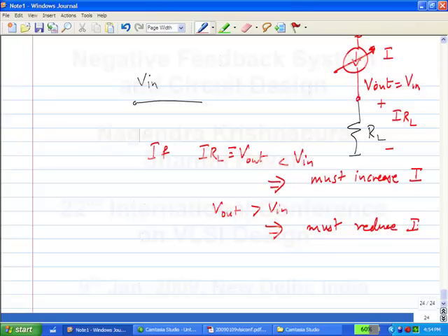Okay. So, in other words, this controlled source here is a current source which is controlled by what? Actually you are sitting and looking at V in, V out, the difference, turning the knob. But in essence, bottom line is that this current is being controlled by the difference between V in and V out. Correct? So this is a voltage controlled current source where the current is being controlled by the difference between V in and V out.